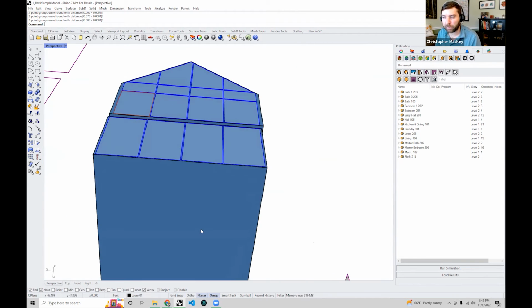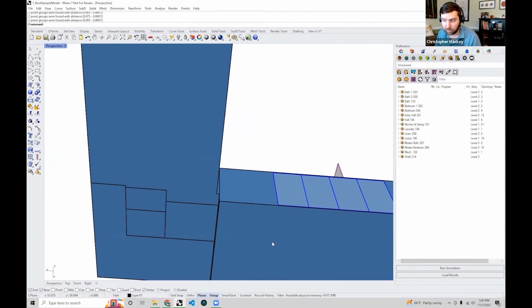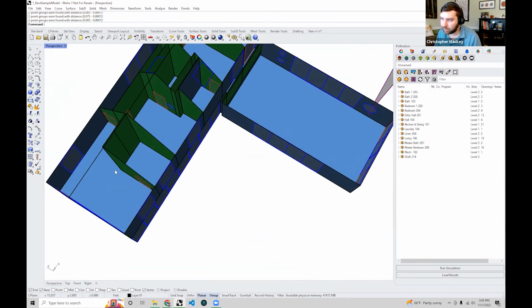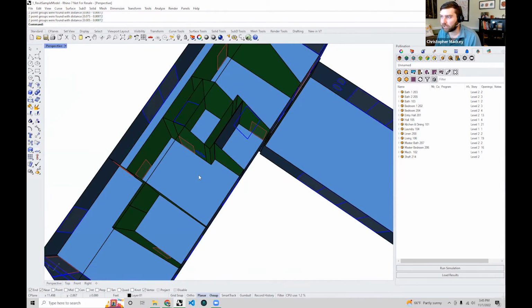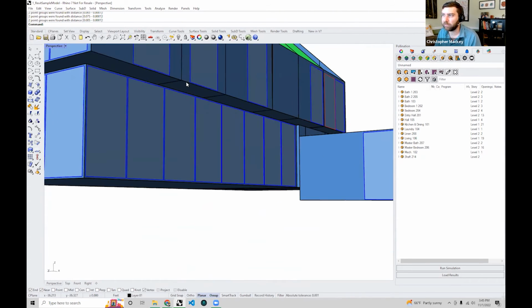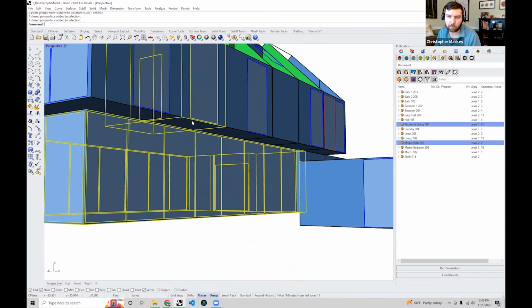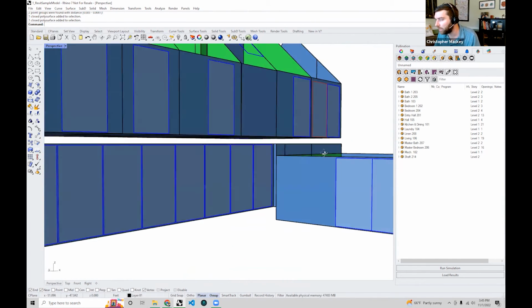So maybe you might be referring to this floor slab that should be in contact with the ground, but also the floors of all these rooms on the second story are exposed to the outdoors here. The reason is because Revit exported this model with this gap between the two stories, which you saw Mustafa fix in the Revit plugin workshop if you attended that.